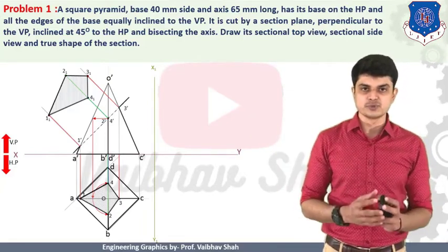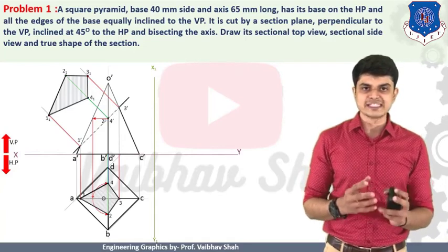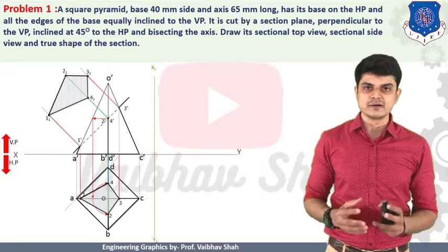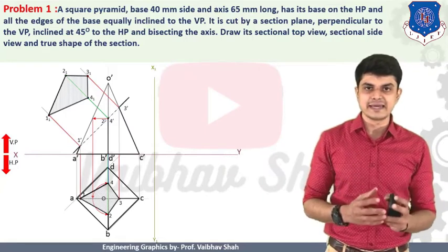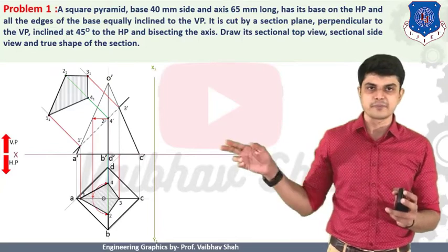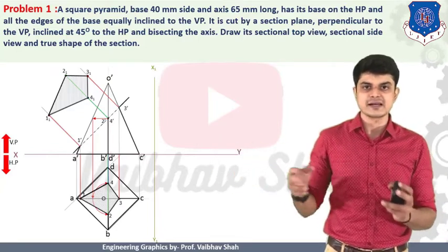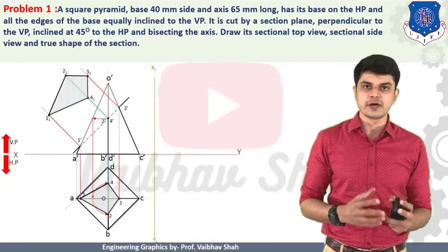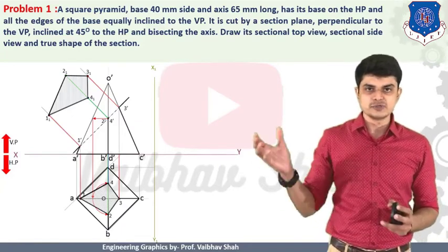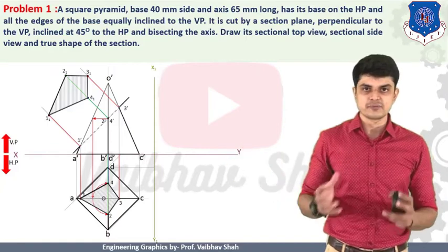So now what should we do? You should draw and transfer each and every point from your top view onto the right hand side of your x1 y1 line, and thereafter take on your rounder the dimension from your center point to that point, make an arc and transfer each and every point onto your xy line. So let us try to transfer point D. You should draw one horizontal line from point D.